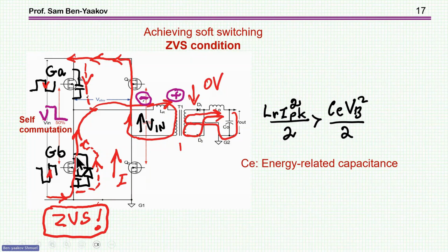And if it is stuck, then when the transistor is turned on, I have losses due to discharge of this capacitor, which is not now zero, but there is a certain charge on the capacitor, into the transistor.